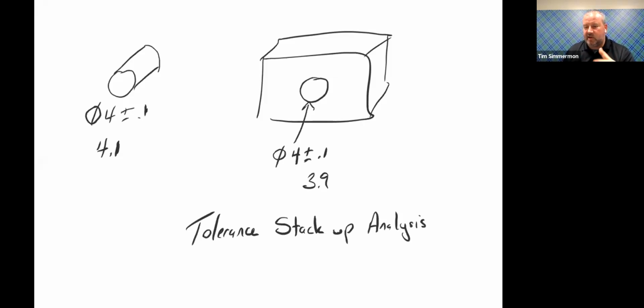So imagine if you're designing an automobile and you're looking at all those components that have to go together into that automobile. And you have to look at pin sizes, hole sizes, you name it, to make sure that everything is going to fit together properly. Not only that, you have to worry about, by the time you stack all these components up together, is it going to be taller than, let's say you're building the engine, and won't allow the hood to close on the engine? So all these things that you have to look into.